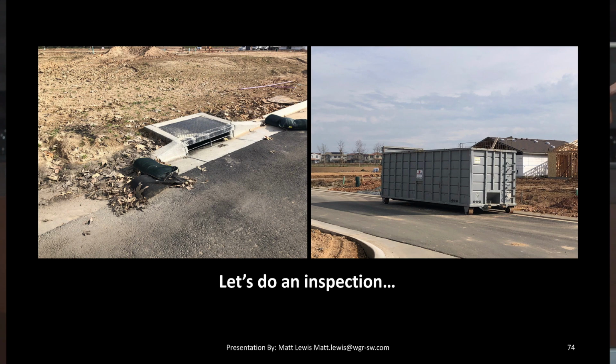When it comes to trash bins, they're supposed to be covered at the end of every workday. So that's my little helping cheat there for you, is that those trash bins aren't covered. And they can actually be considered discharge points, usually with the trash container. You're going to want to tip them up just slightly at the front, right? Because imagine if that thing's getting filled with trash and all kinds of stuff, and it gets filled up with water, or whatever water hits it and just starts flowing out all that beautiful trashy water. That's technically a discharge point that you would need to sample.